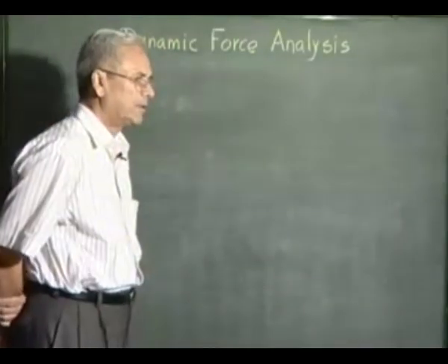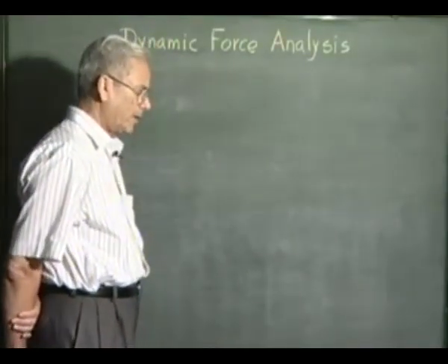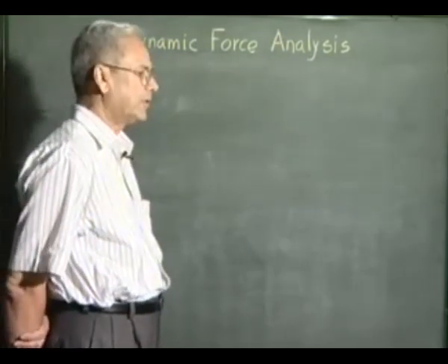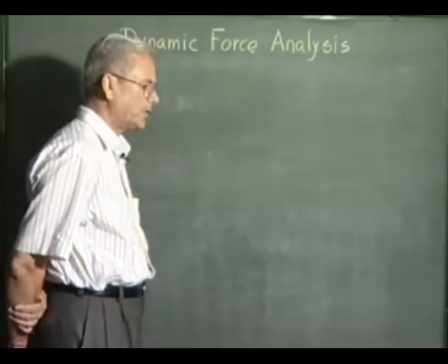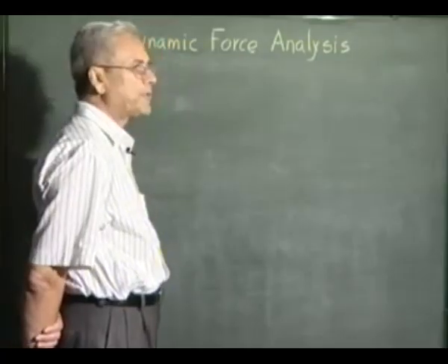Now, in the previous lecture, we adopted a technique of using graphical procedures. Though we get answers which are often adequately accurate and precise for design purpose, it becomes very difficult if we have to repeat the analysis again and again for a large number of situations. For example, if a mechanism is continuously rotating, say a crank rocker mechanism, then to find out the forces for the complete cycle, we have to repeat the force analysis for each and every position of the crank. Maybe if you have to take the cranks at every 2 degrees, then we have to solve the problem 180 times.